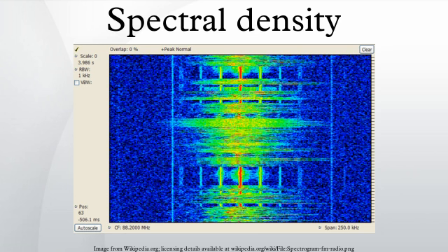Intuitively, the spectrum decomposes the content of a signal or of a stochastic process into the different frequencies present in that process, and helps identify periodicities. More specific terms which are used are the power spectrum, spectral density, power spectral density, or energy spectral density. The variance has units which are the square of the units of the signal. Therefore, these are also the units of the spectral distribution, and so the units of the spectral density are the square of the units of the signal per unit frequency.